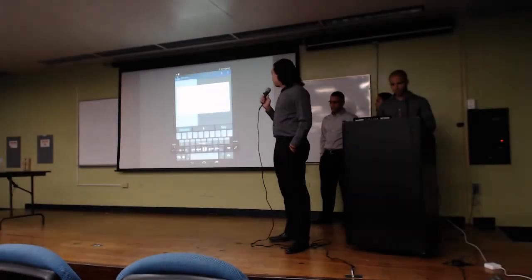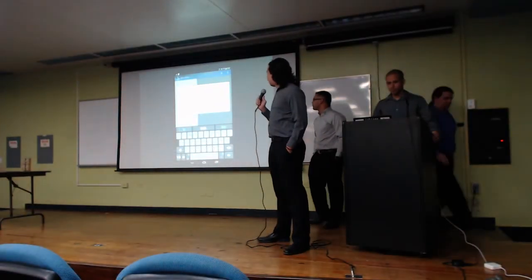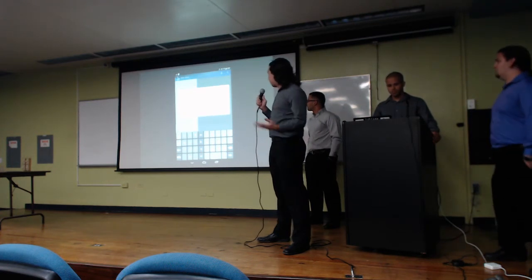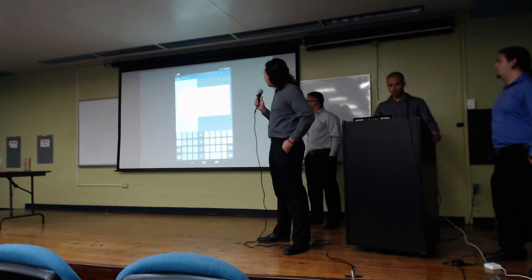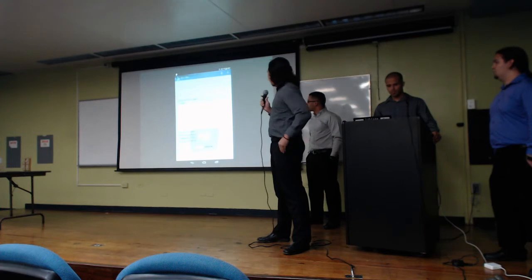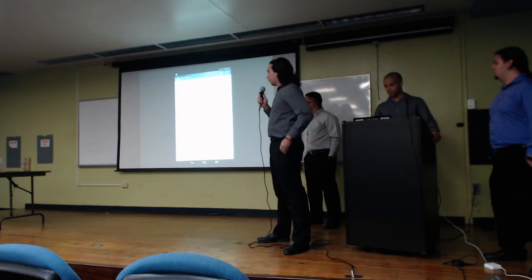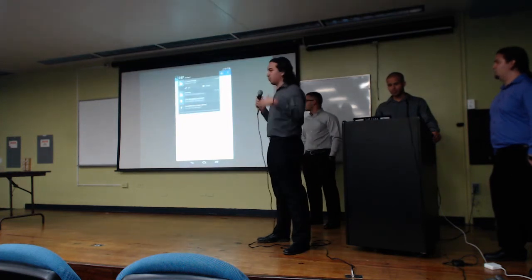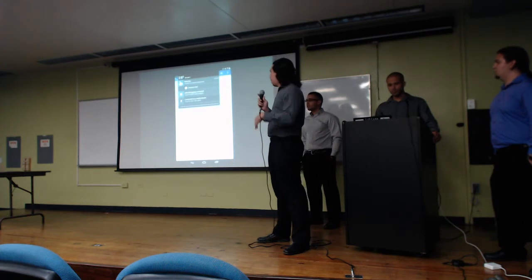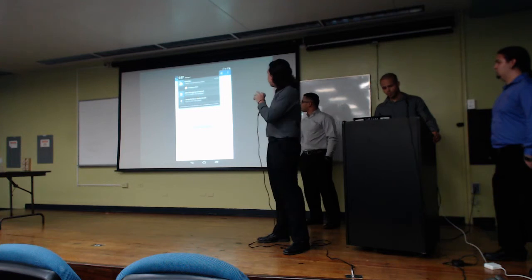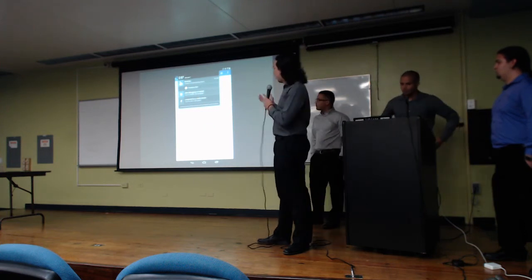So this is the application. As you can see, it's entering the experiment name, the wind speed, samples. We have 3 samples for speed, and the time interval between samples. That's the basic data. So that's the Aerobal controller via Bluetooth. Start your run. The application will seamlessly show you the wind tunnel, ask you if the wind tunnel is empty for calibration, it's running, it will then send an emergency as needed. Right now we're going to show you a dual display of what is actually happening in the system right now.